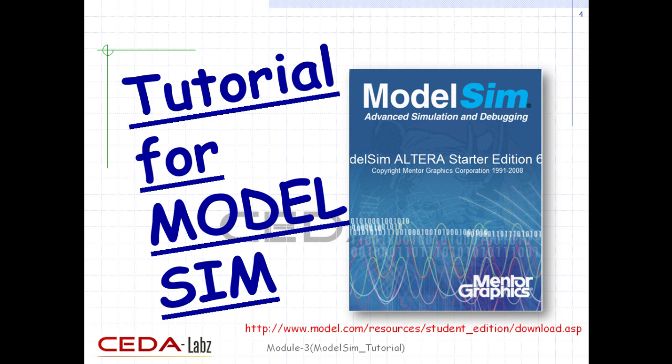to you via email. Once you have received the license and everything has been properly installed, ModelSim should execute without issue. Navigate to the Help PDF documentation pull-down menu and select Tutorial from the list. Thankfully, ModelSim has provided a simple explanation on the basic use of the application. Read through and follow along sections 1, 4 and 6 using Verilog. Note that ModelSim tutorial will not instruct you on the syntax/use of Verilog.